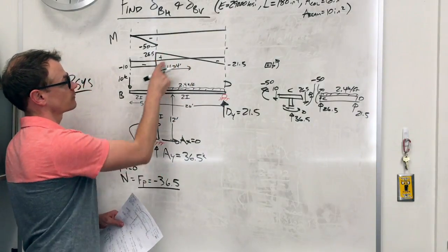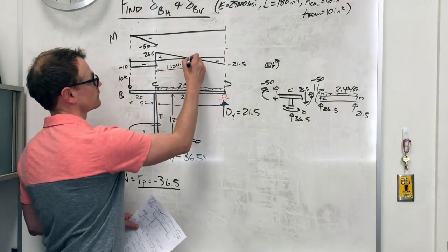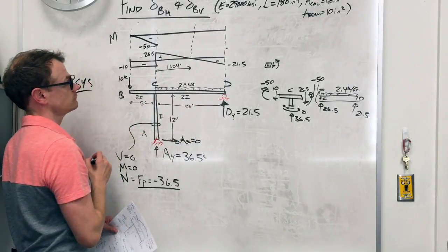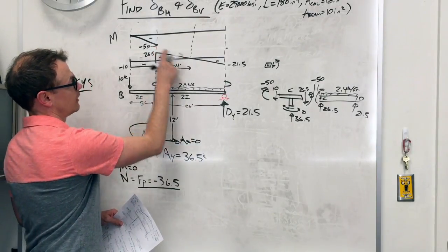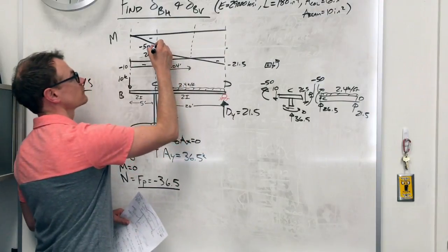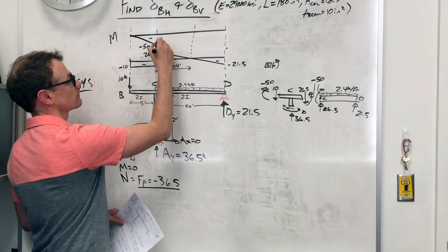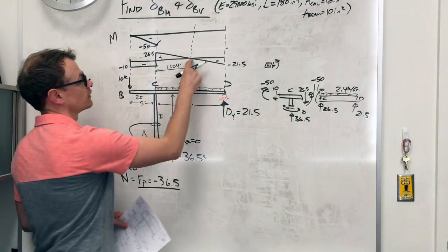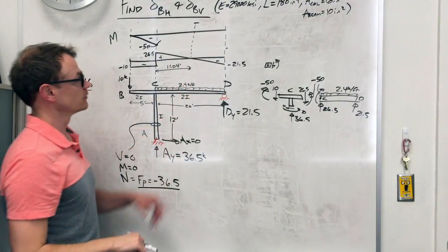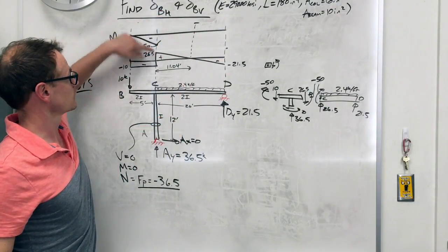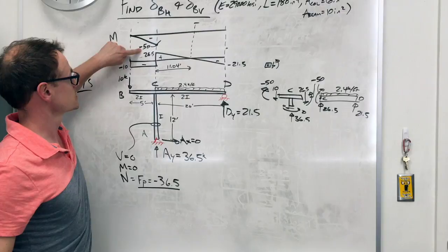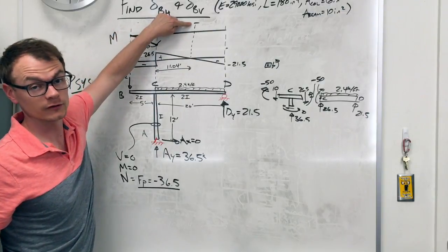So now I have this one, that's my shear. So that tells me something about the moment. I just confirmed that it starts at negative 50, so I'm going to start at negative 50. I have a positive slope. Here I have 0 slope. And you can do the calculation here to see how much does it change from negative 50 up to where does it go.